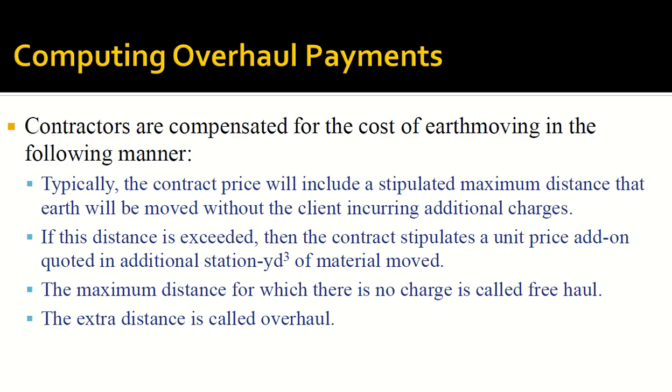Now you tell the contractor, okay, my project is balanced. Take material from here. My fill quantity is equal to cut quantity. Everything is balanced. So I will not give you any extra payment for filling or cutting, or any extra payment for material, because you are taking the material from one point and putting it on the other point. Okay, makes sense?